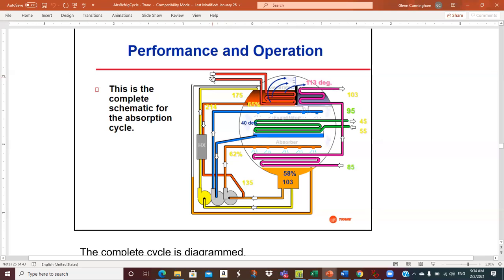I think typical is like 12 PSIG steam. Hot water, roughly 200 to 250 degrees, something like that for a single stage machine. We also have two stage machines that require 350, 400 degrees Fahrenheit, in excess of, I think, something like 100-pound steam to drive those cycles.